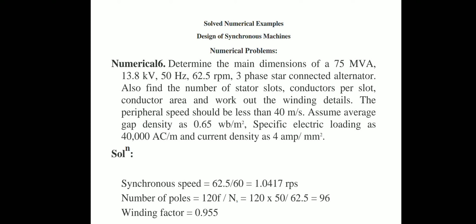And the winding factor, we have to choose the winding factor. We know the winding factor is 0.955. As a design engineer, you should keep in mind that the winding factor is 0.955 or in this range.